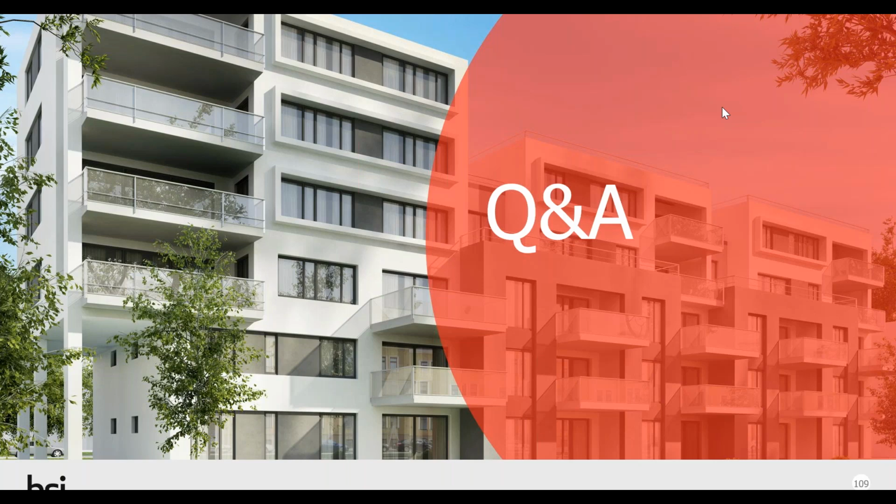I've already covered some of this. The standard refers out to BS 9991 and BS 9999 for that requirement. It doesn't add anything further to that, apart from a commentary that the designer should consider the effects of the deformation of the balcony on the building, and to minimise the risk of the balcony becoming detached in the event of a fire. But apart from that, in terms of the actual fire performance of the structure itself, it refers out to 9991 and 9999. Great, thanks for clarifying, Tony.